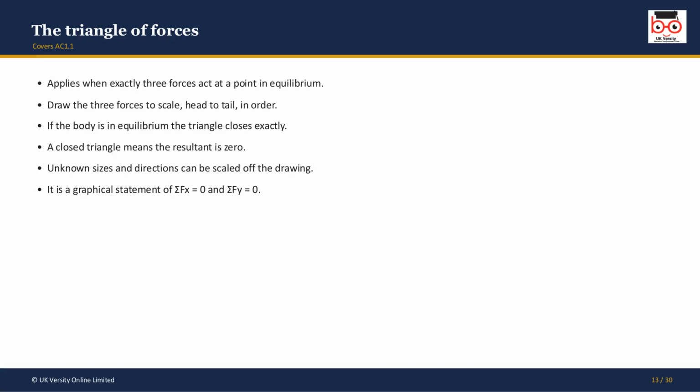Let's look at the first graphical tool, the triangle of forces. It applies when exactly three forces act at a point in equilibrium. You draw them to scale, head to tail, one after another. If the body really is in balance, the triangle closes perfectly.